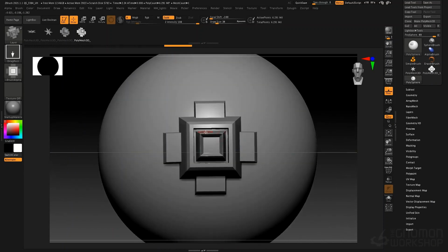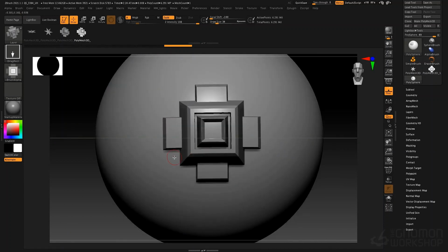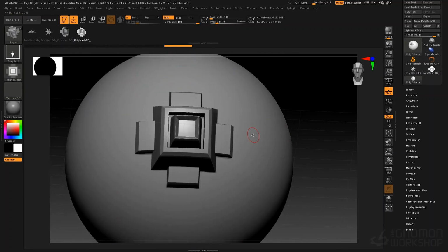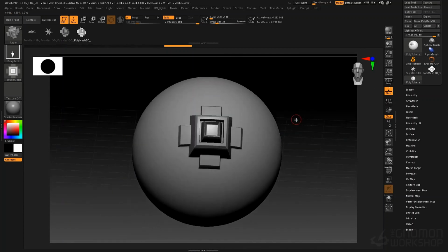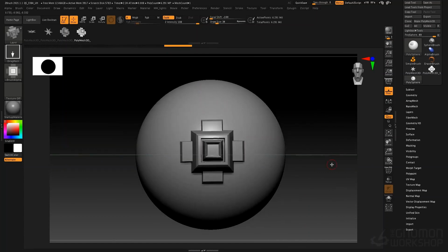You can make it less pronounced as long as it's not an exact 90-degree angle. If you want something that is a 90-degree angle like that, I would recommend using a vector displacement brush, because it will give you a better result than the grayscale alpha, even though the vector displacement brush is usually associated with things displacing around a 90-degree angle, around a curvature.